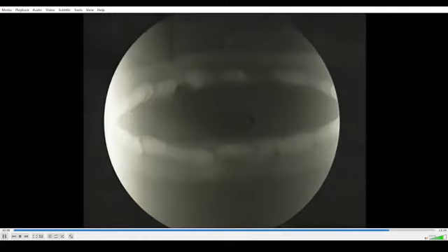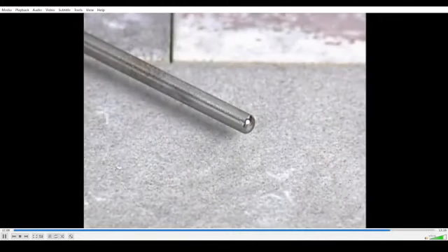prone to tungsten spitting. Pure and zirconiated electrodes for use with conventional square-wave power sources should have rounded tips equal to the diameter of the electrode for best performance. If the tip becomes too large, it produces an erratic arc that dances around the surface of the ball.